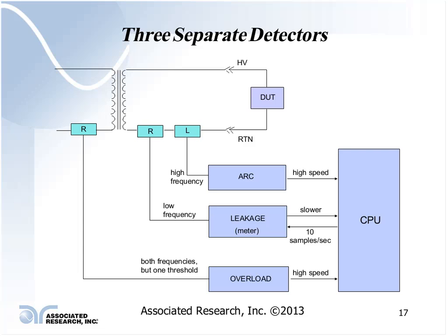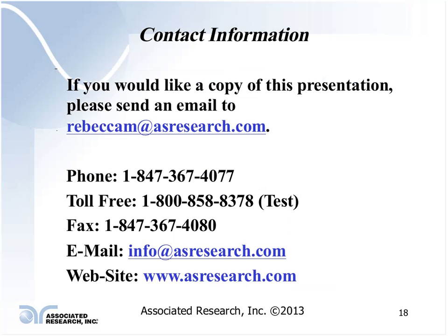If you have an arc fail in conjunction with an overload, where you've exceeded the maximum capacity, the display on the unit is going to say breakdown. If you have just an overload, that essentially if you had a short circuit in your device under test, this detector is going to go off before anything else because it's on a high-speed shutdown, and that will give you an OFL type failure indication. So depending upon which one of these detection networks is going off in combination with any others, we can give you much more information on what is going on with your device that is actually being tested.